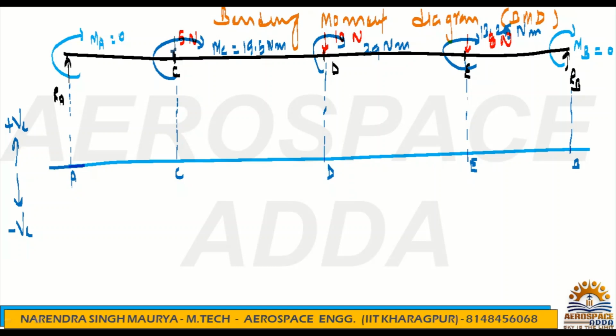table I had given. For the bending moment diagram, between 2 points, if there are points A and C, in between A and C we have only point load. At A also we have point load, and at C also we have point load. We do not have any UDL or UVL. So for the point loads between A and C, if you draw the moment diagram, it will be inclined. I have given one table. If you check, you will get it.